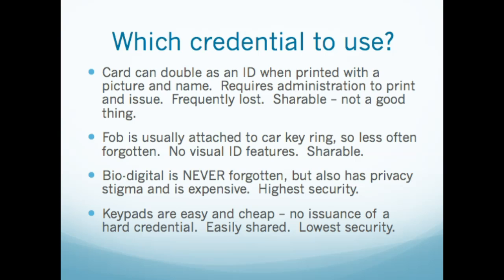The actual card reader, when you use a badge, is about $200 out of the box. That's not the installation cost and everything, right? That can go up to $5,000, like I said, but just the reader itself is usually around $200 for a proximity reader, the ones that you just hold the badge up to. For any type of biodigital device, I've never seen them less than $5,000 just for the device, be that iris scan or high speed fingerprint readers. They're all $5,000, $6,000, $7,000 each. So there's a big cost to those.